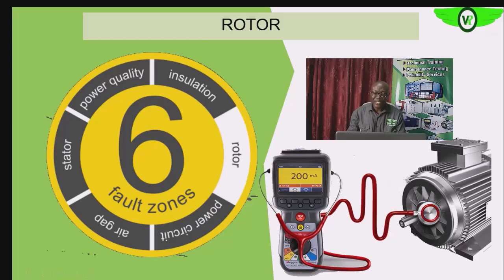Okay, we use the Mega tester MTR105. The MTR105 can actually assist us in doing this, because we check the inductance. The rotor influence, how the rotor position changes, affects the inductance of the stator winding. Are we getting it? So as we rotate, we take the reading, and we'll see the rotor influence on that inductance.